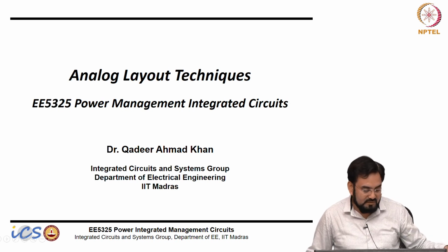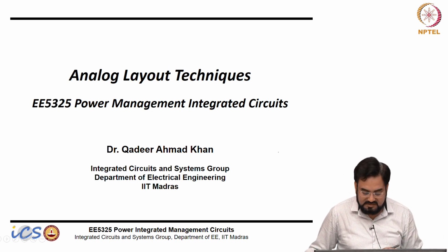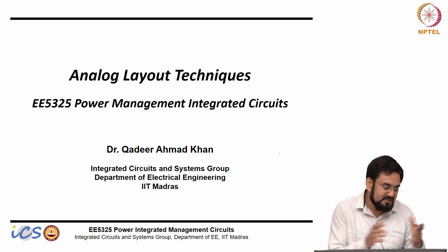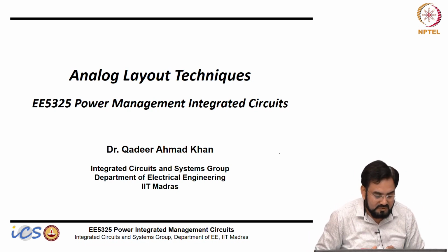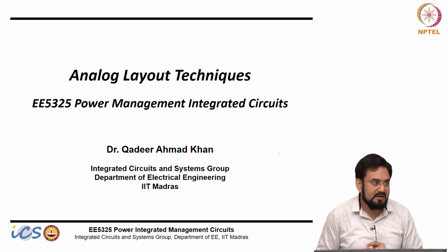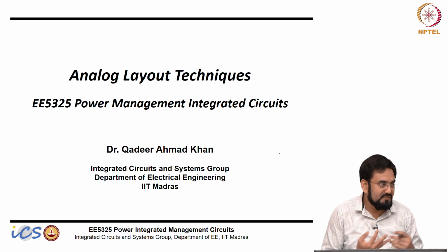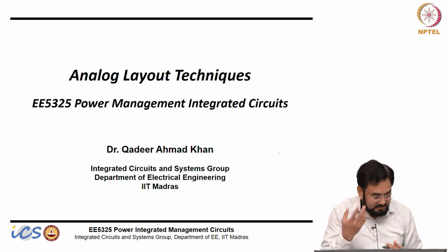Okay, so we'll look into layout techniques today. In order to do the layout for any analog, and obviously the PMIC falls into the analog category, you should know what the different analog layout techniques are, because you have to design op amps, power FETs, and band gap references.